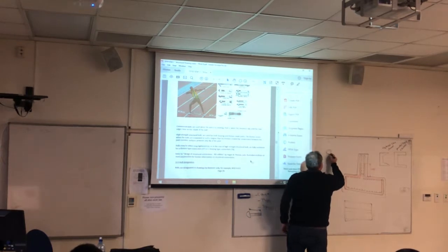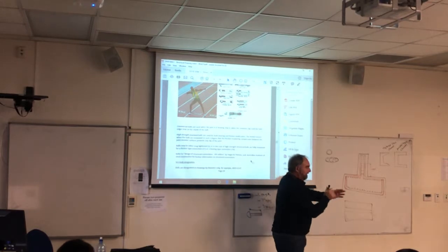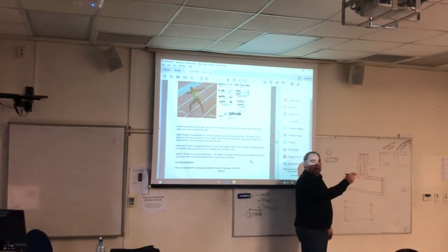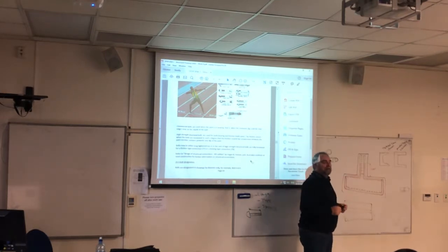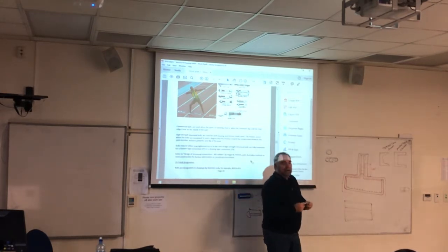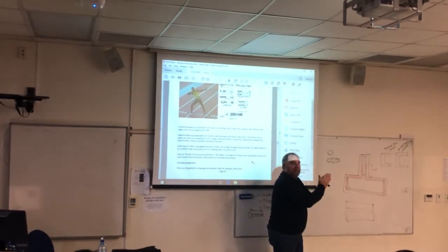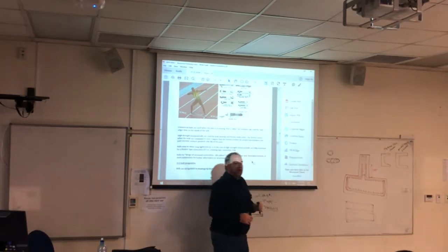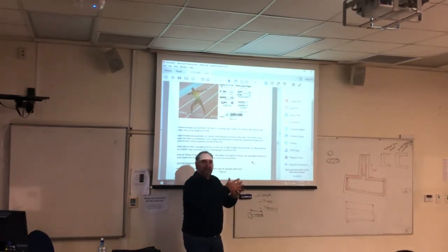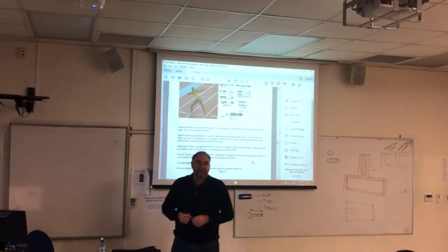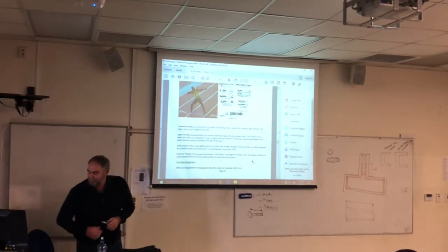A friction type joint is going to be something like this. So you've got a bit of play over to where the bolt goes, and it's often used where you're lining it up with another bolt on the other side. You need a little bit of play to get it perfect. And also that joint allows a wee bit of movement, a bit of friction, where you know that the member's going to be expanding, contracting, or perhaps even moving at the same time.